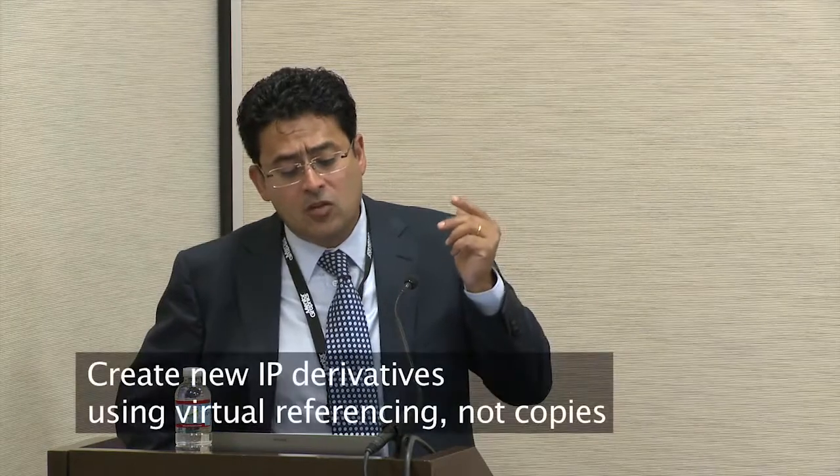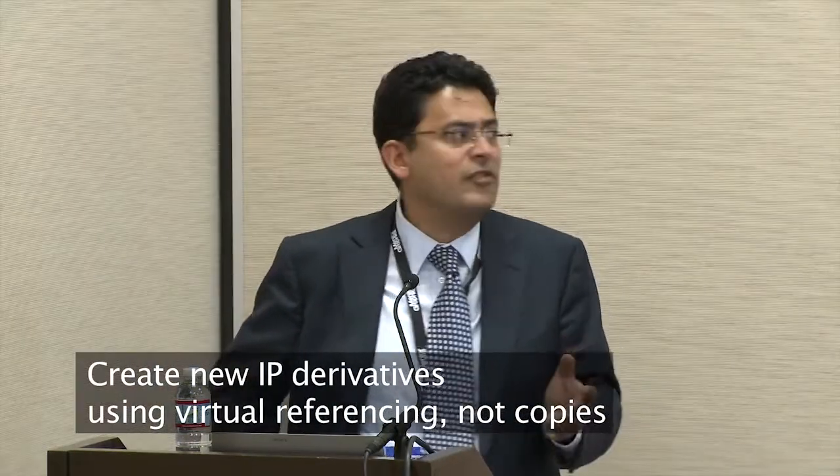So you really want to use a top-down approach. And then, create your IP derivatives using virtual referencing or branching, so that you can track and figure out where everything went. The key to doing that is that when you use virtual copies, you can understand where everything went. So if I reused a block in 6 different chips, I have a record that I can simply get a report from, and I know exactly where it went. I don't have to go in and open the schematic or the RTL, or even on the FIB machine try and identify what the layout or PNR of a particular block looked like. And we've all done that. So the key is to get away from it.